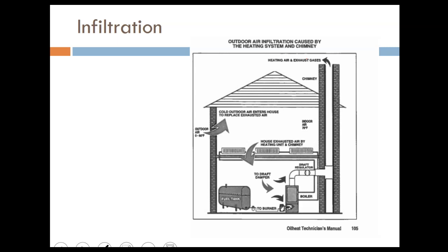This is the infiltration that we count on to provide air and supplemental air into the boiler. And think about that when you do an installation, and think about that you don't want any completely sealed basement, because a sealed basement provides no air for combustion and provides no air for the draft regulator to work with.